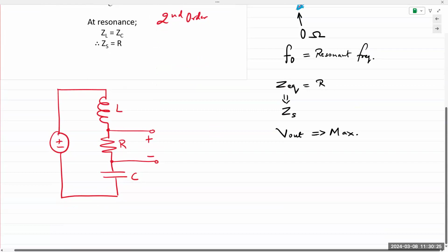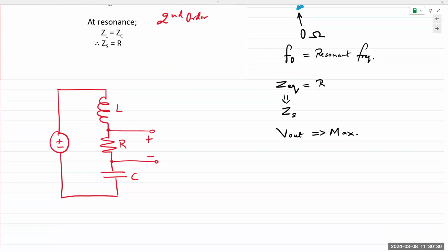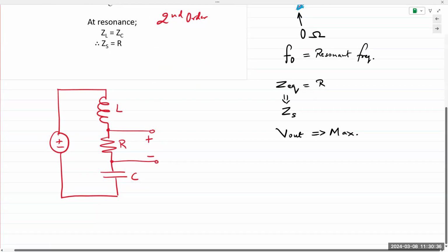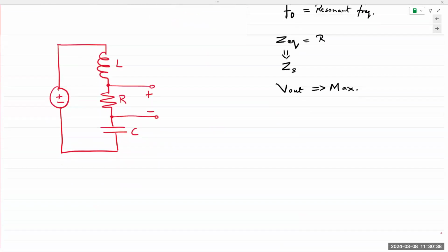If you have both a high pass and a low pass filter in the same circuit, and you bring both of them together, you get a band pass filter. So the characteristic of a high pass would look like this. This is a high pass filter, right? This is pass. This is all blocked, right? All frequencies higher than the cutoff frequency are allowed to pass through.